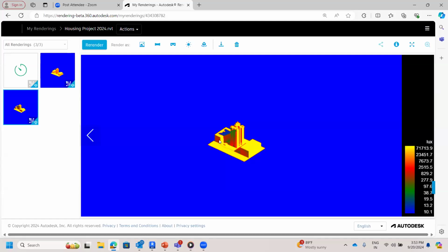Similarly, you can see on this end that the building has a particular shade from this particular mass. So this predicts that for the particular time, we cannot install panels on the roof of this building. So we need to plan either vertical facades or some other alternatives, right? This sort of analysis it gives you.